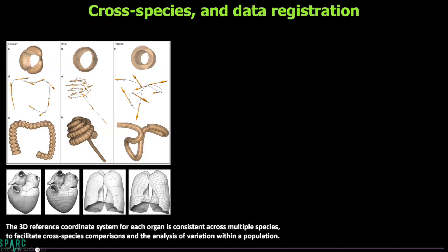We develop scaffolds that represent the geometry of the heart with subtle variations in terms of the number of pulmonary veins returning to the left atrium, for example, which can be typically 3, 4, or 5. But other than that, the topology is the same. Then we can refine these meshes to export them depending on the resolution that's needed for capturing data or the resolution needed for capturing the physics, using computational physics to understand the function of these organs.